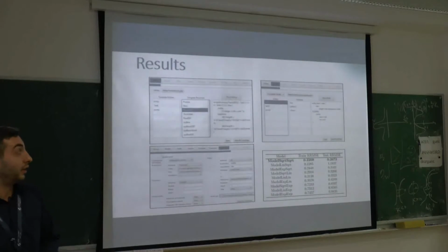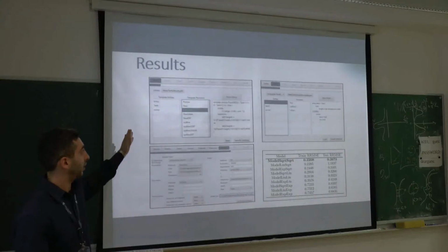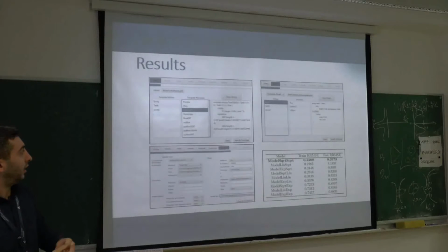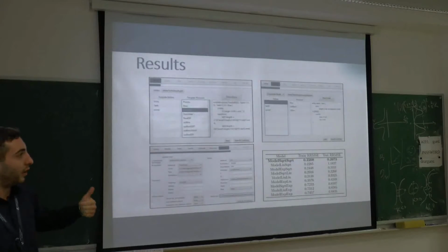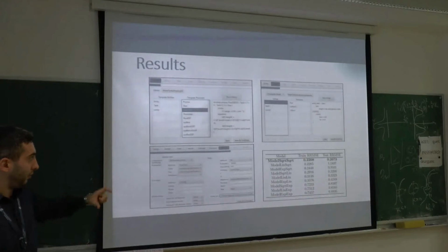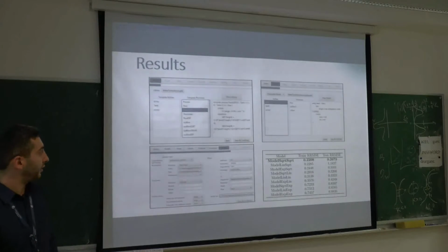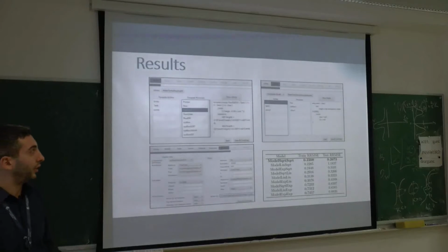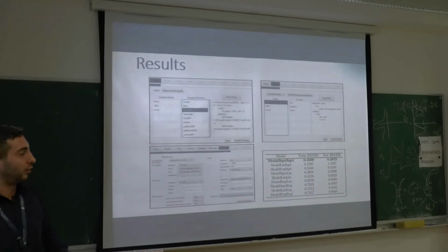This is how it looks in the ProbMod GUI. As we can see in the library, we have defined the three behaviors of the water, the square root, linear and exponential behavior of the inflow, outflow, and the mutual flow between two tanks. And we define our particular task. We say that it consists of two tanks and one pump, and we don't know the particular behavior.